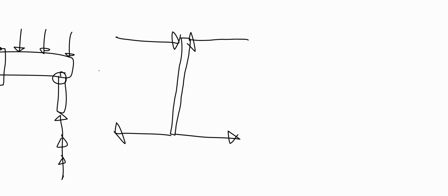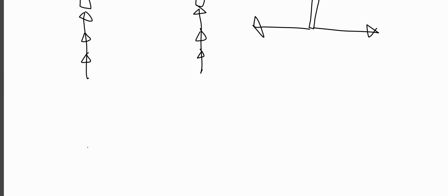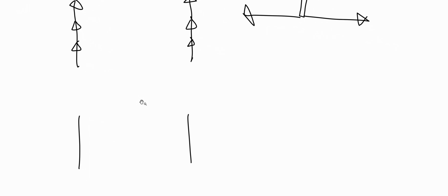So the center of this beam is essentially not being stressed in terms of compression or tension. That's really what's going to break this. The bottom of the beam, it's like these wood fibers are being pulled apart. And the top of the beam, it's like they're being pushed together. If you ask why, you can imagine that it makes sense because when you load something that's supported over here and it deflects downward, like it would bend under the weight, then the material on the top of that beam is getting crammed into itself, and the material on the bottom of the beam has to stretch out in order for that shape to change.